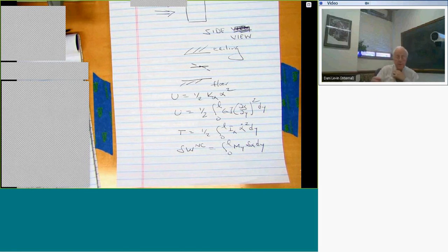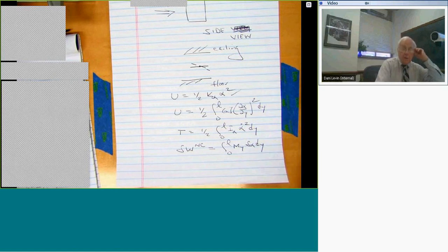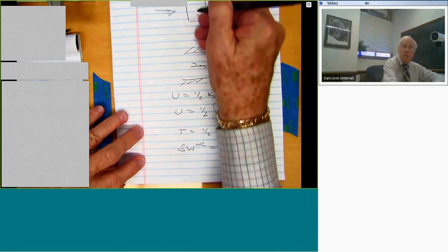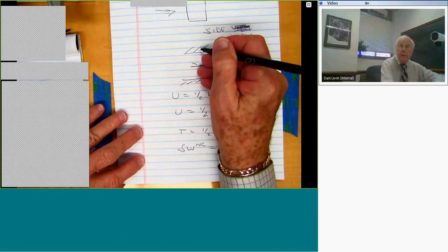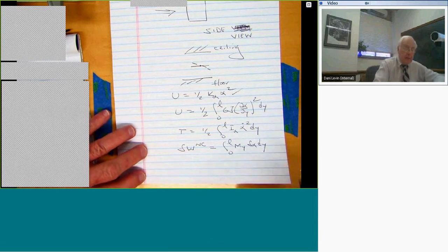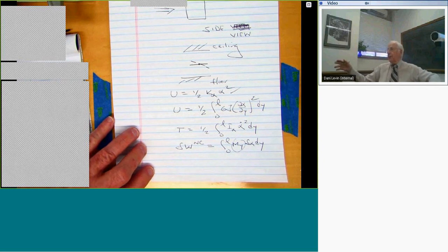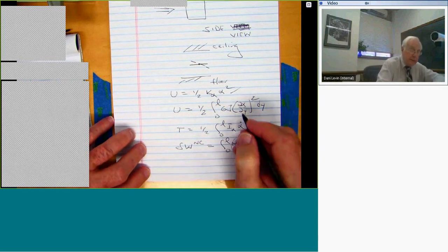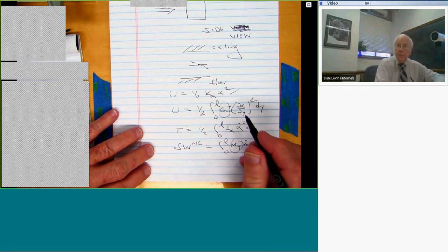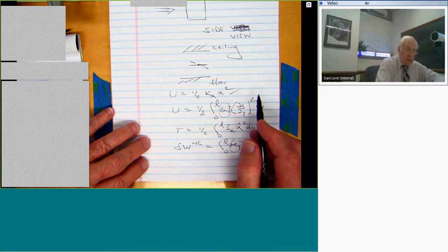Now, I have to be a little careful here because this I alpha isn't quite the same as when we were doing this model, because this is the I alpha per unit span. It's the distribution of moment of inertia along the span. So it's the usual units of I alpha per unit length, right? And this is now the moment per unit length, too, along the span, the aerodynamic moment per unit. GJ is the torsional stiffness of this wing or this piece of metal.